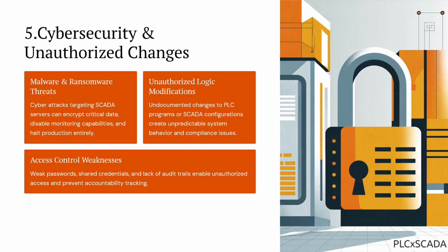The next one is unauthorized logic modification. Verbally changes to the PLC and SCADA may invite infinite uncontrolled loops in the PLC and SCADA application, which results in interruption in production. So always we have to remember that there should be proper documentation or a change control policy for the modifications.